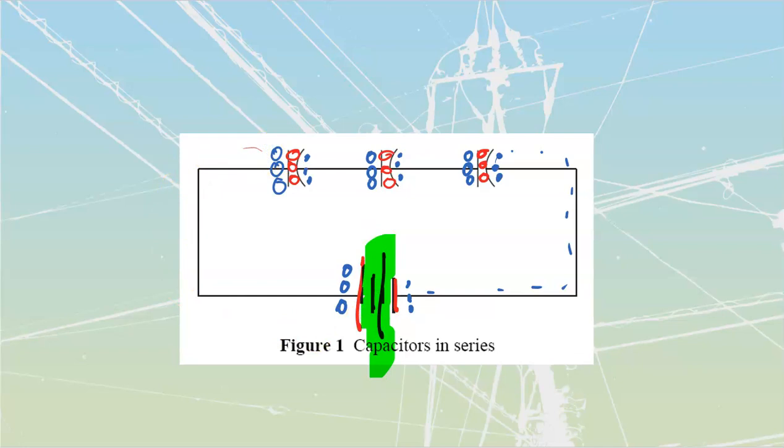When we close in, there's going to be that brief instant where we see our current spike and then taper away, and as the current spikes and tapers away, the voltage over top of the caps is going to rise like that. What you'll note about it is that the Q, the amount of coulombs that I'm going to put into here, is split up now across 3 separate capacitors, right?